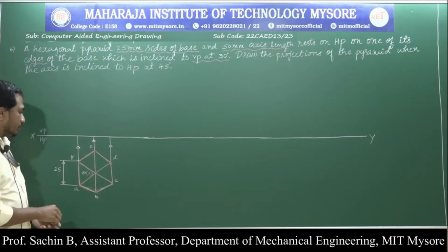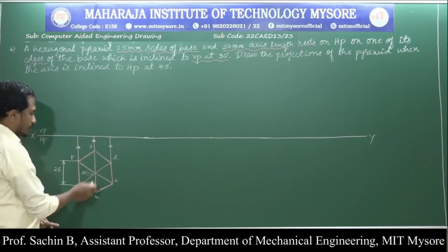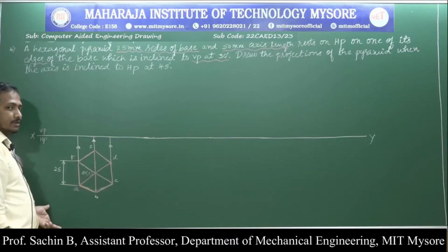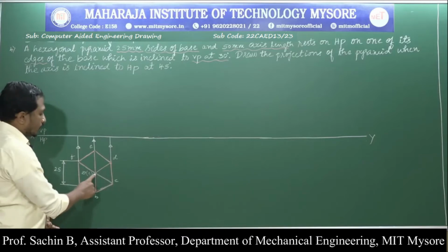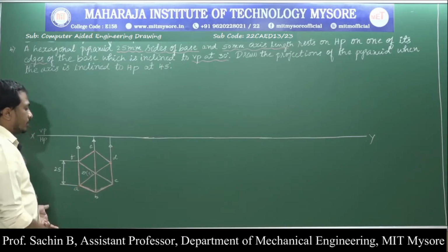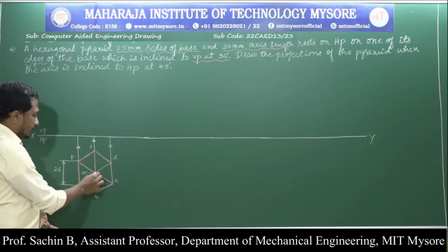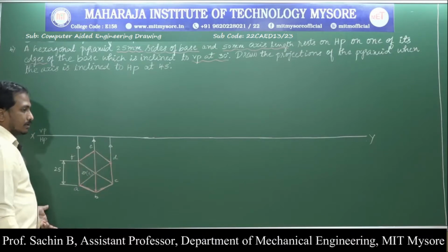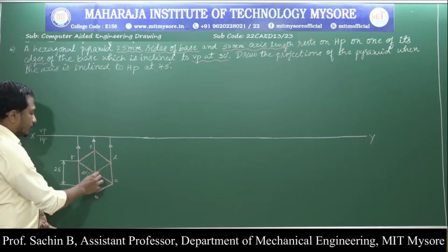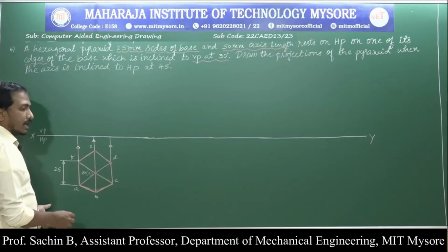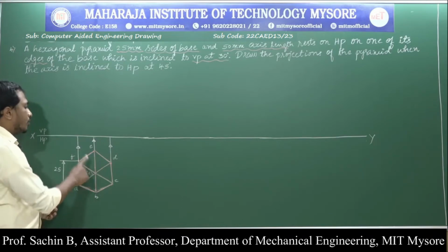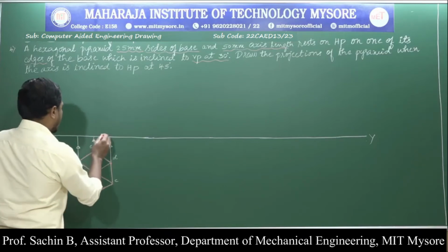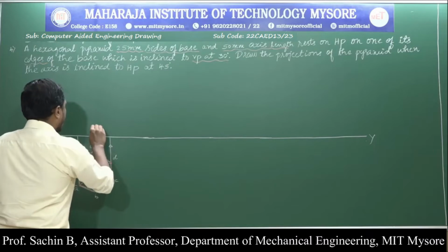Now in the front view, the slant edges connected from the base to the apex point, O to A, O to B and O to C, are clearly visible for us. The slant edge O to B overlaps the edges opposite to it. O to B overlaps the axis O to O1 and also O to E. Based on that, I am going to construct a visible line.